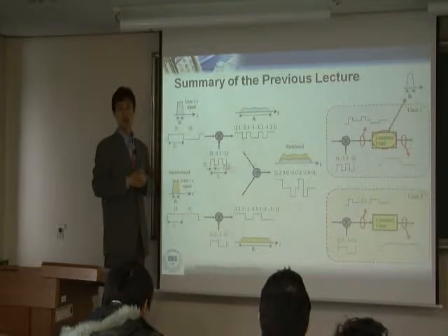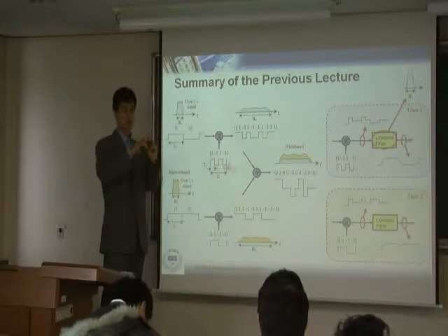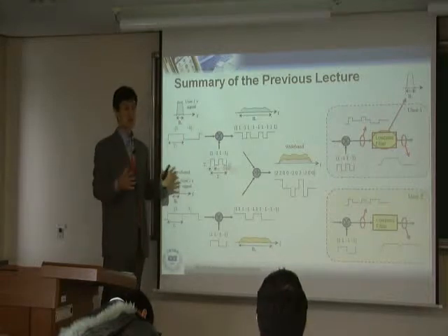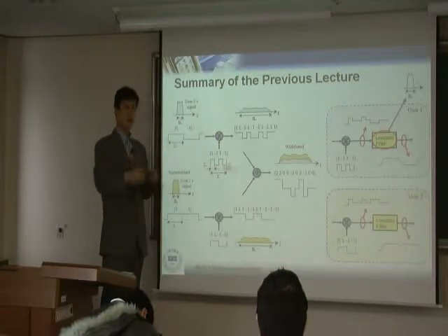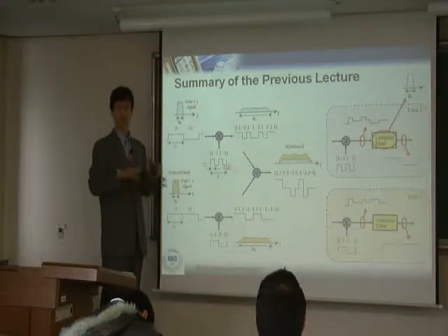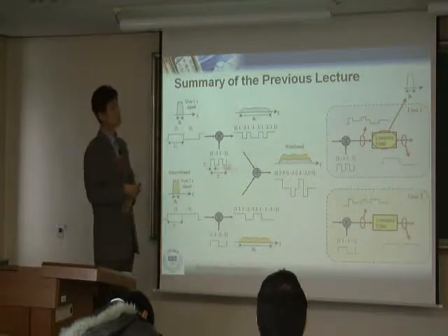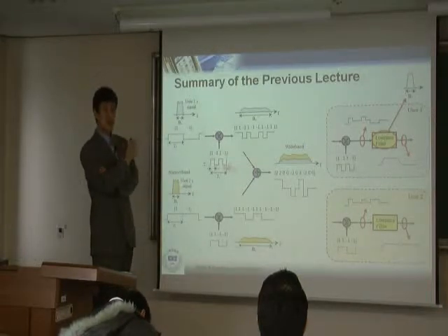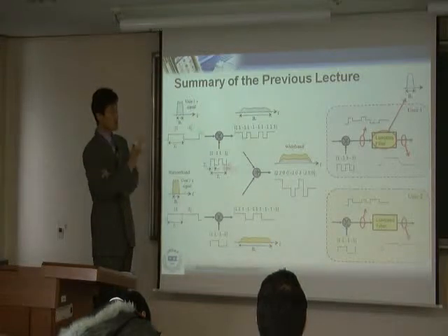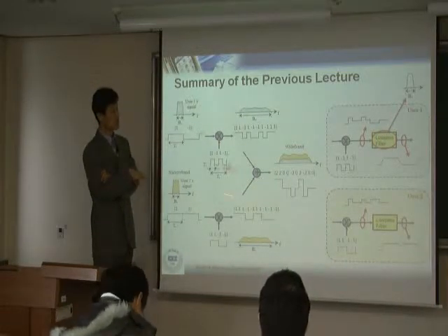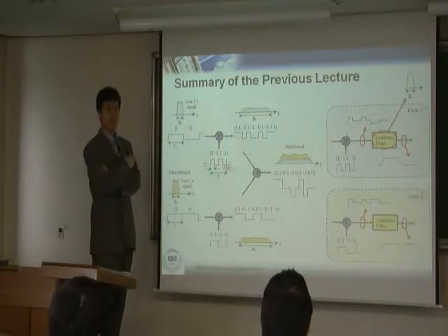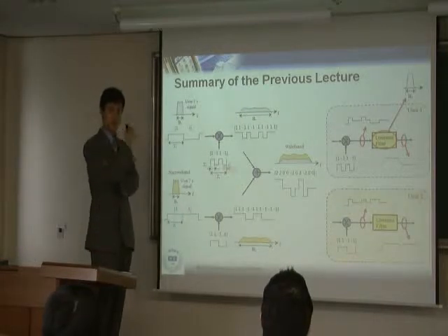That's a closed loop. So always you have an open loop power control and a closed loop power control at the same time. First open loop and then later the closed loop. You always have two of them at the same time. Especially in CDMA, that's a very important thing. Without this kind of power control, this system never works. Very critical. And even the OFDM system has closed loop and open loop power control. Same concept is still there.